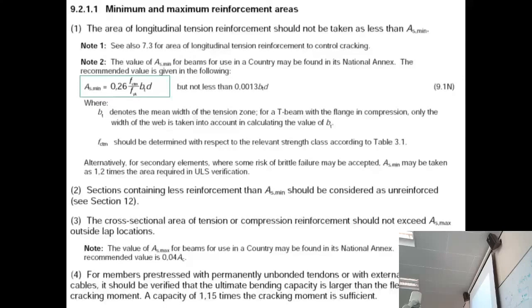When we designed the cover, we had steel in it. Now we're redesigning the steel. So how do you start? In the British Standard, you used to do the cover last. The reason that you do the cover first is if we've got a beam, we need to know this value D. To find that value D, you've got to know your cover and half the bar. That will help you find the value of D, because the bar radius can change the value.